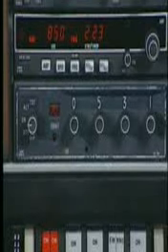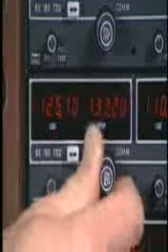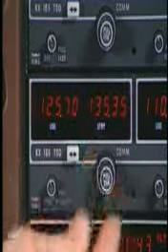Instrument high altitude and route charts must be used for navigation in Class A airspace. If you're using VOR navigation, your aircraft must be equipped with DME for flights above 24,000 feet. It's important to note that a transponder with Mode C altitude reporting capability is required when operating above 10,000 feet MSL in all controlled and uncontrolled airspace within the contiguous United States and the District of Columbia. This excludes the airspace at and below 2,500 feet AGL.